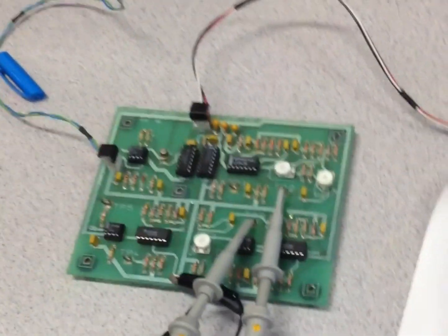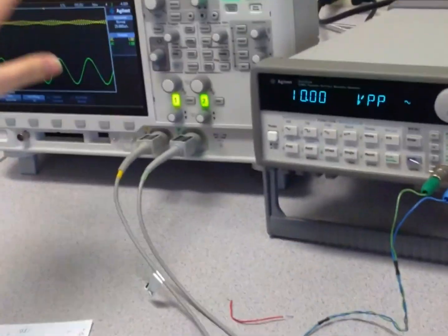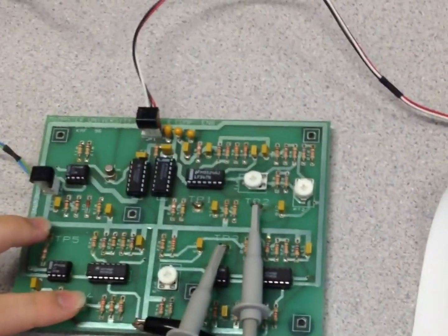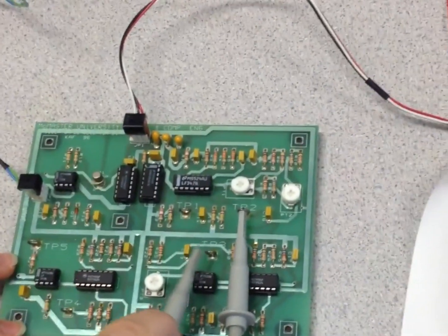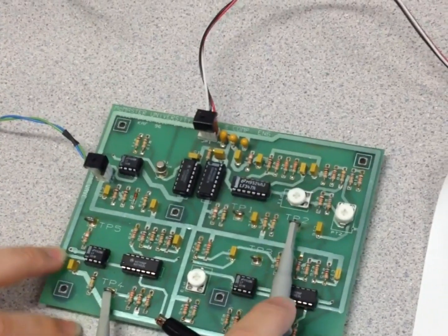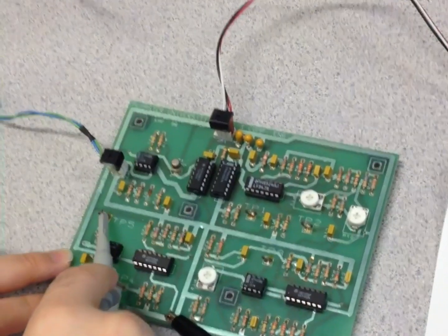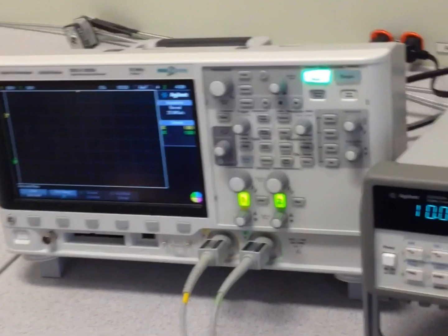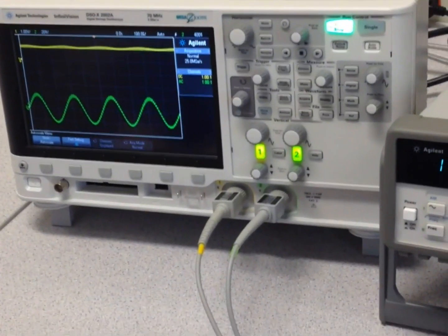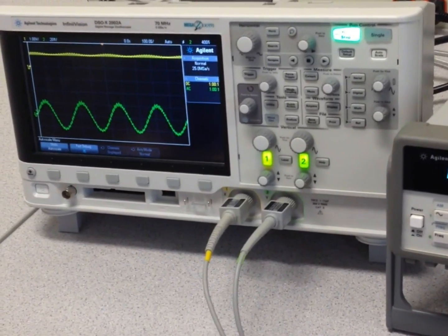Okay, so this is our message multiplied by the carrier. Now, TP4 is after, this is the receiver part, after multiplying by the carrier again, and TP5 is after the low-pass filtering. Let's see 4 and 5 and see why they are not as good as we expect. Let's again auto scale. Not good at all, right? We could try to make it slightly better.